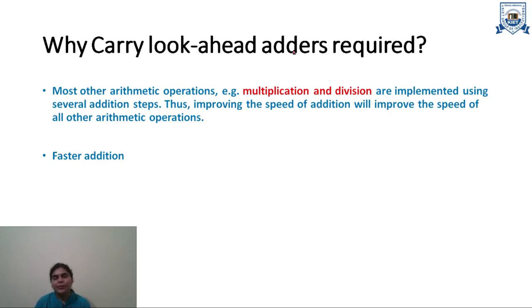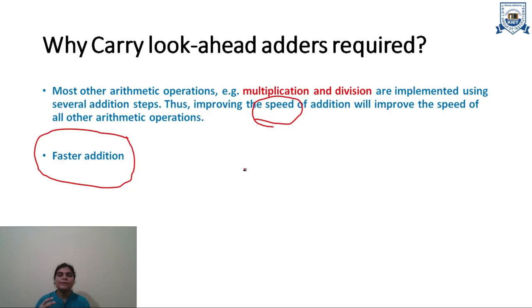To speed up arithmetic operations, we need a carry look-ahead adder, because it reduces the carry propagation delay of a ripple carry adder and provides faster addition. In digital circuits, speed is a major concern. The carry look-ahead adder gives faster addition, but on the other hand, it has complex hardware circuits.